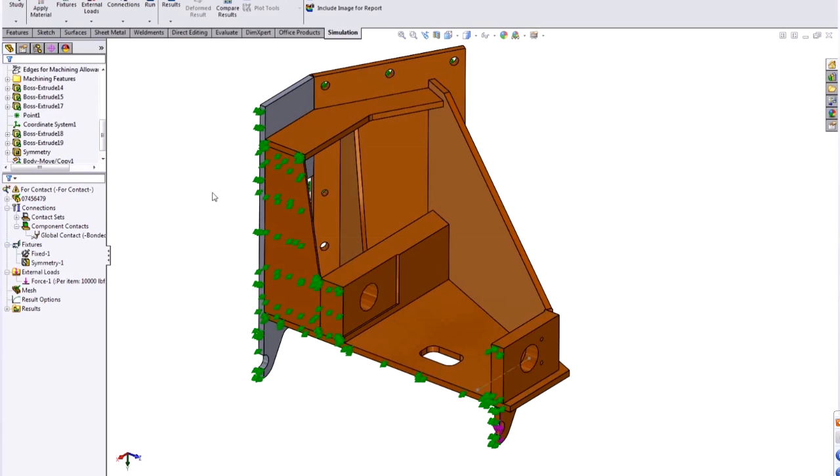Now, the software won't do anything automatically for faces that are not touching. A common thing we hear people say is, I mated them together a quarter inch apart to allow for a weld, so why aren't they tied together in the analysis? Stress analysis doesn't look at mates at all, by design. There are many situations where you have a mate that shouldn't be a connected relationship. It only looks at where the faces are touching.